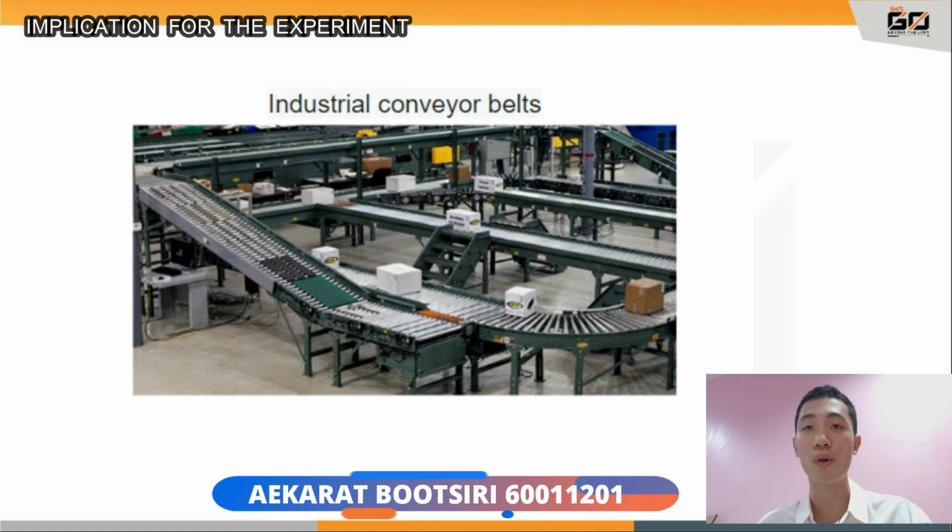For example, in the industrial factory, we control the speed of the conveyor to transport items, starting and stopping the motor. From what our group has said earlier, this is an example of driving the induction motor with an inverter in a mode of constant torque control, which is used to control the conveyors.